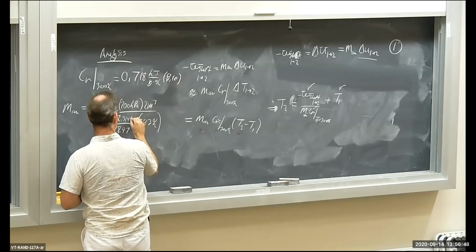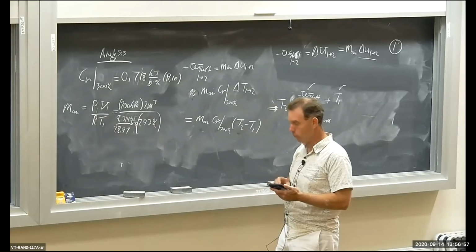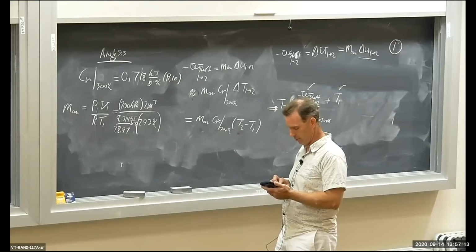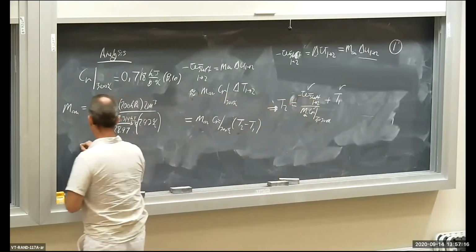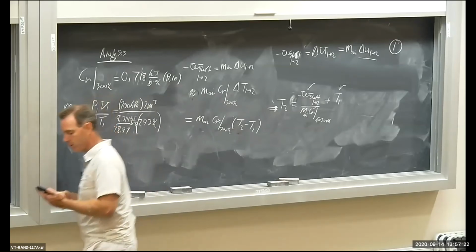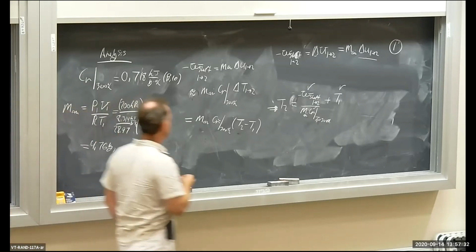So this will have units of kilojoule per kilogram degree Kelvin. The kilojoule and the kilopascal will cancel out. So we should have kilograms when we do this. Let's see here. 200 times 2 divided by 8.314 divided by 293 times 28.97. And I get 4.76 kilograms. That's my mass of air, 4.76. Okay? All right, so I got everything. I got the mass now.